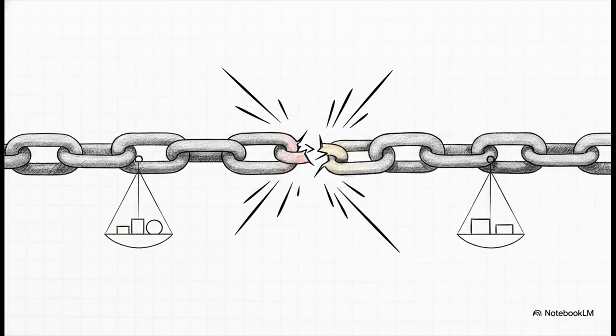So how do engineers actually measure true success here? Well, they calculate something called joint efficiency. And it's a pretty harsh reality check, to be honest. The efficiency of your joint is based strictly on whichever of those 4 failure points is the weakest link. You calculate the absolute least amount of load required to cause any of those failures, and you divide it by the load the solid uncut parent plate could have carried on its own.